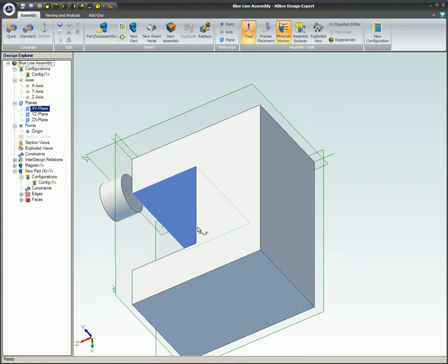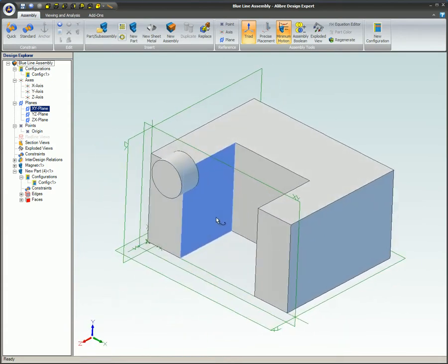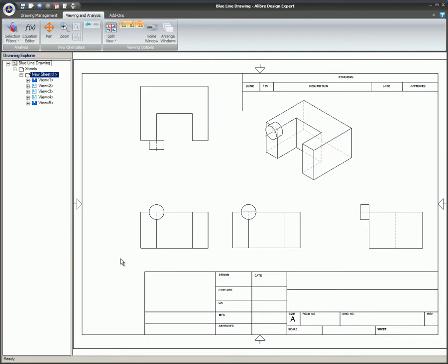Since fast views show the actual model and not the projection edges, there is some functionality that cannot be done. Shown here in segmented line figure is a simple two-part assembly that demonstrates this behavior. The isometric view shows Part A and Part B. Since Part B is in front of Part A, it covers up a portion of the edge. The actual length of the edge is 448 thousandths, but because of Part B, the edge appears to be only